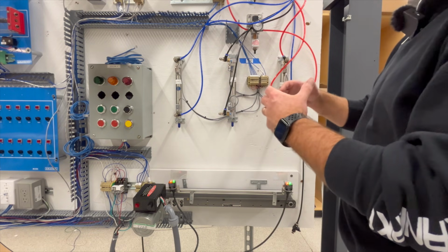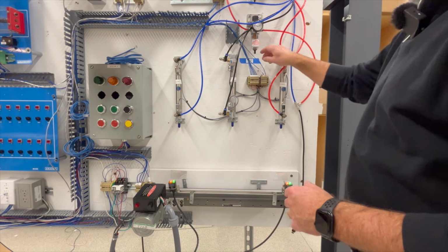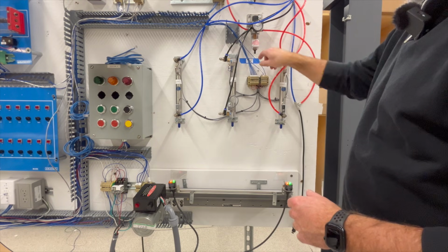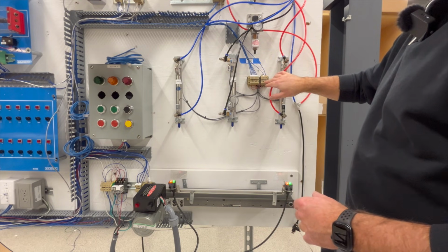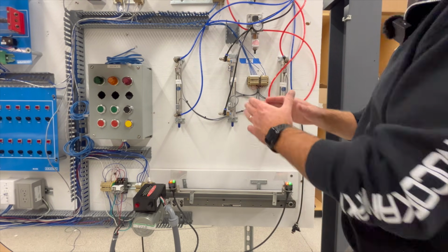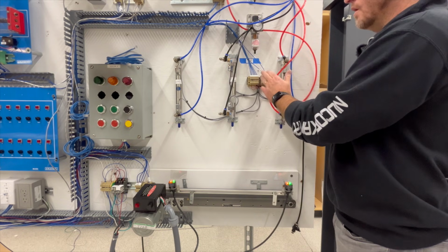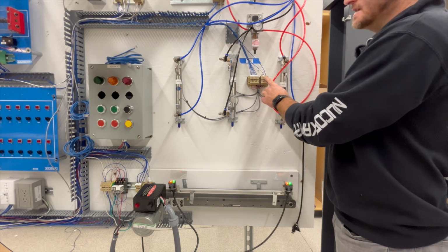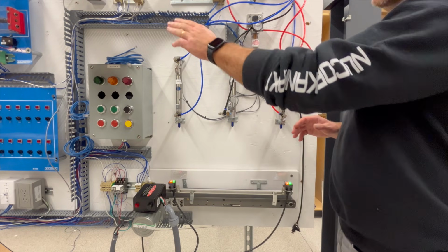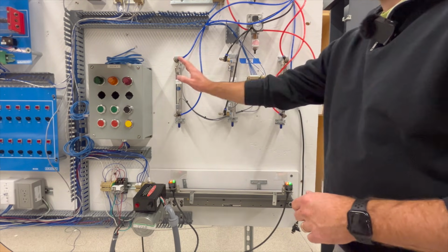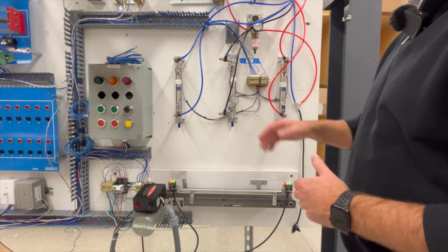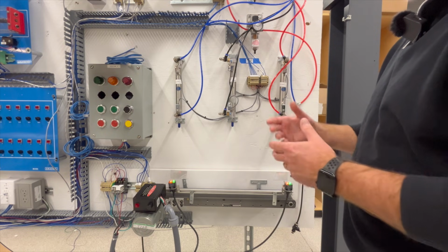Well, the common between them would be the 24 volts being supplied down to here. And that would have led me down checking for the 24 volts positive here, and not the common here, but just because all 4 of these were not activating properly, that sent me down a different path.